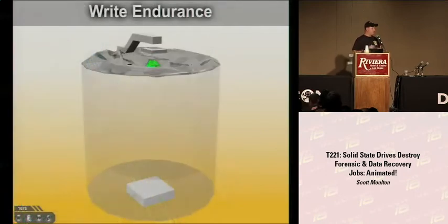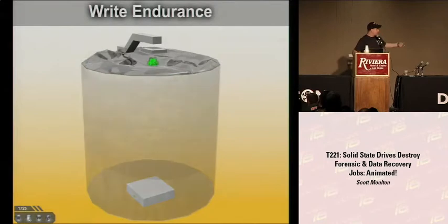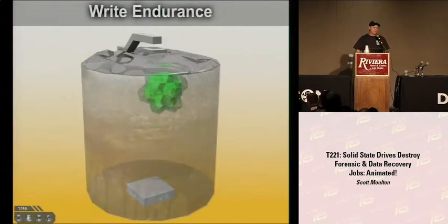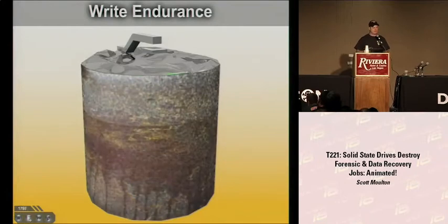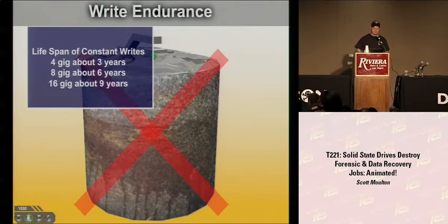So this is what we're talking about and why we're trying to protect the chip and basically not destroy it: write endurance. Every time something is written into it, it physically is starting to destroy the silicon in the cell over time. And the discussion seems to be, how many times is that going to take? Sometimes some vendors are saying it's going to take 100,000 writes. 100,000 writes before it dies is the typical answer. But some of them are now saying 1 million. Some of them are saying 10 million before it actually dies.